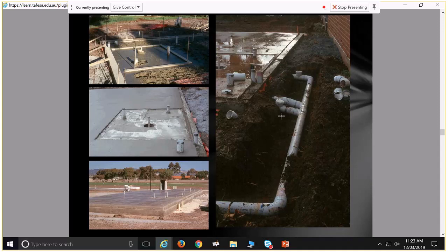So when we pour the concrete slab, we don't produce the slope. That's something that has to happen very carefully. So what you do is you produce a set down, and then you get all those slopes in there later on with the concrete screed. So, a cement screed. And then you lay your tiles on top of that. So when it comes to specifying what your set down is, you need to think about how much height difference we need between our highest point and our lowest point.